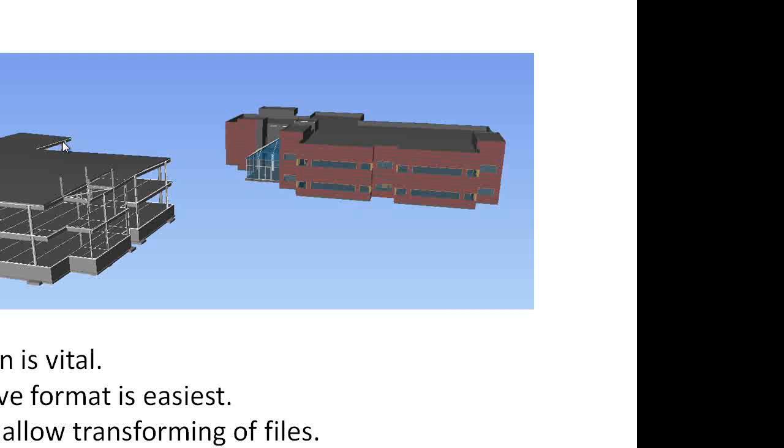When you open files up, it's very common for files to not align correctly. One may have been moved, somebody might have changed the XYZ coordinate values. Sometimes they're even rotated out of position. You can relocate a file within the scene either by a precise distance if you know it, or by applying a transform directly to the item in the selection tree.